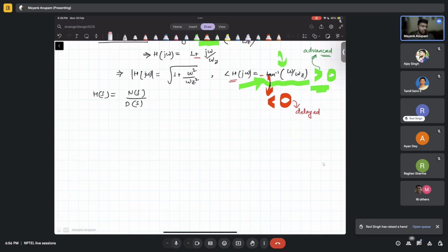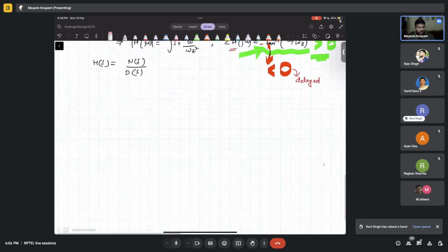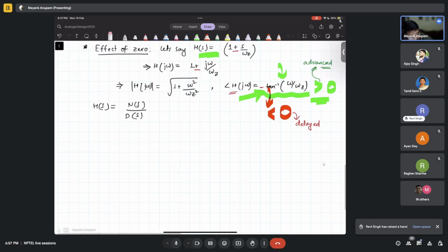In fact, there is a compensation also. There is a feedback compensation you will not learn in this course, I don't think. You will learn Miller compensation in the next lecture, or maybe next week. I don't know, but Miller compensation makes sure that the poles are pushed away. But there is another compensation to make the feedback system stable, which ensures that there is a zero in the system, and that makes the system faster, right? So this is routinely done, whatever you said.